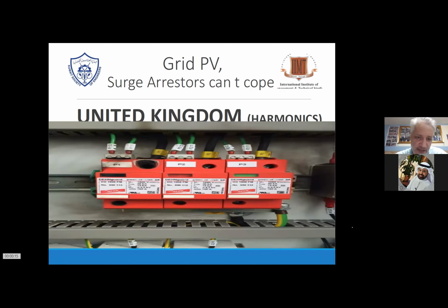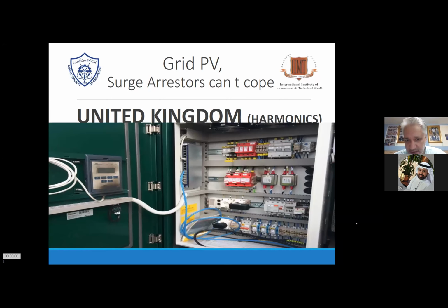So whenever the field pushed current backwards from the transformer or from the field, it burned out either the SPDs on the DC side or on the AC side. You can see here the whole equipment burned down on the data logging side. And also the fuses on the left-hand side for the power box.